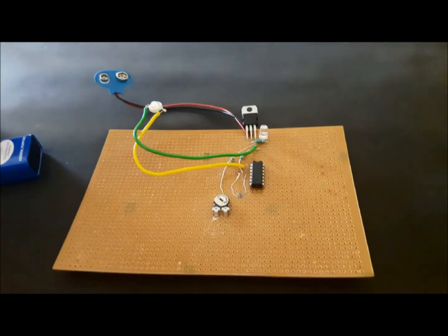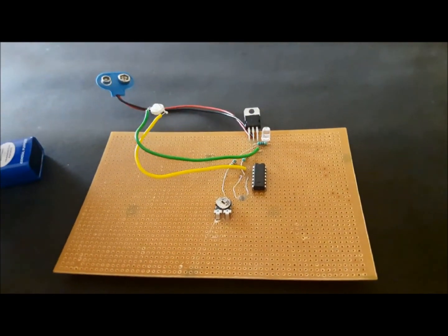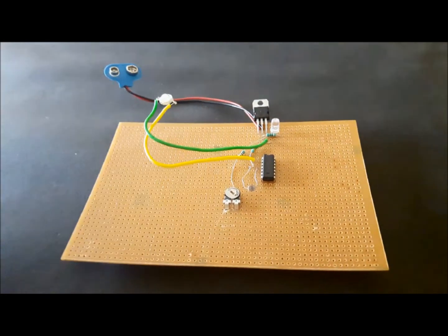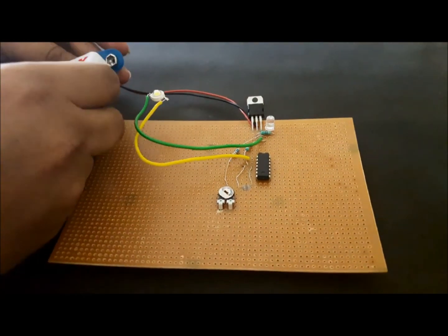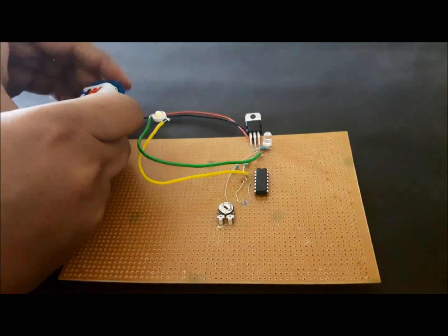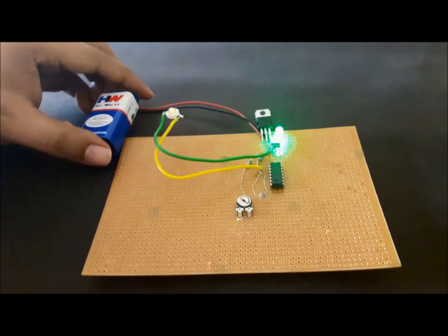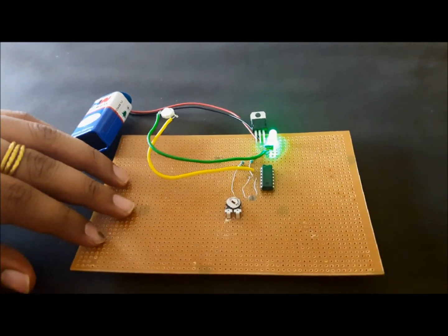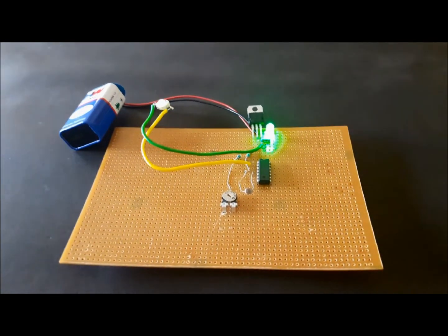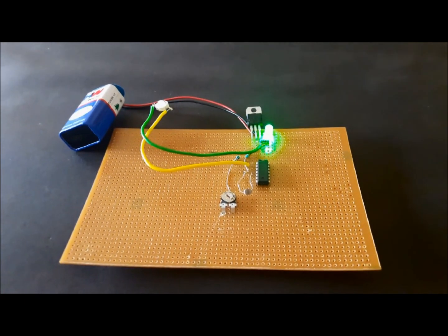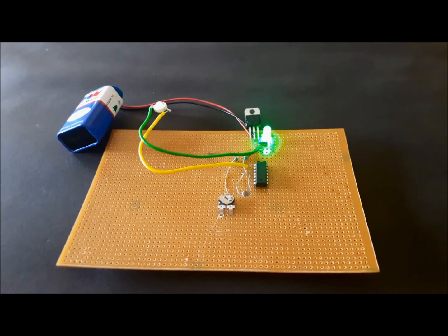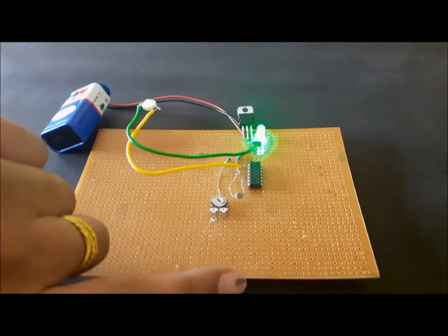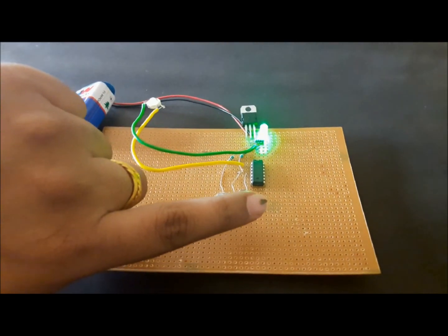You can verify the functionality of the automatic street light control by observing this video. So in this video I am making use of a LDR. See, when I bring my hand closer towards the sensor, the presence of light is been decreased and thereby it turns on the LED. Once I remove my hand, you can see there is a light that is falling onto the sensor. This way the LED is off. By this way we are able to switch the LED on and off by looking into the brightness on the sensor.